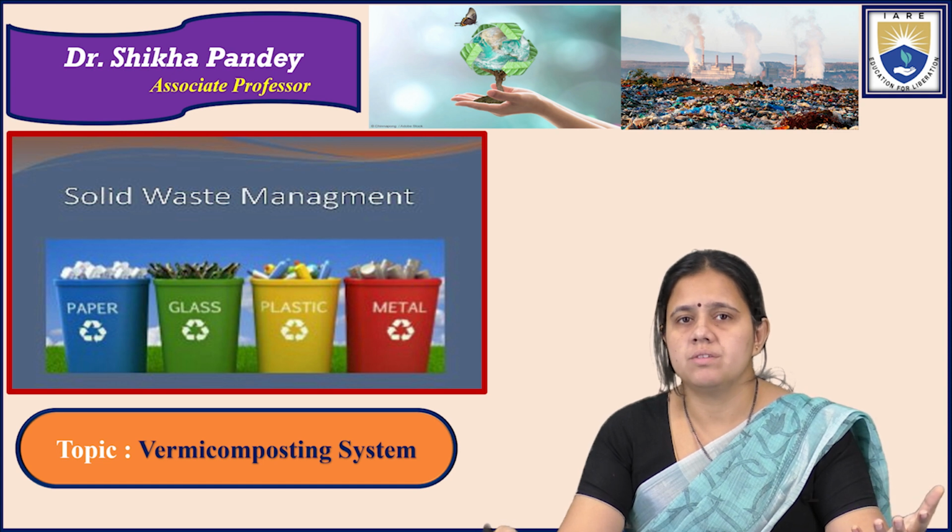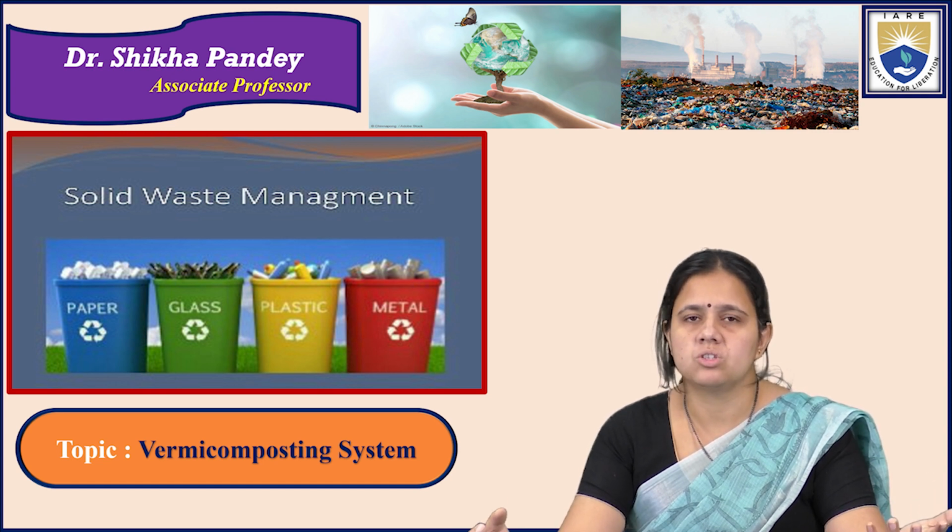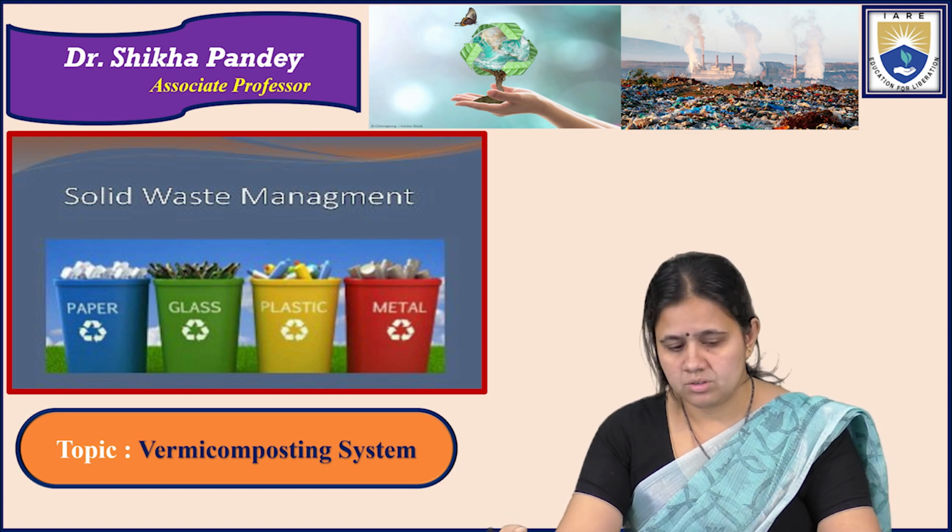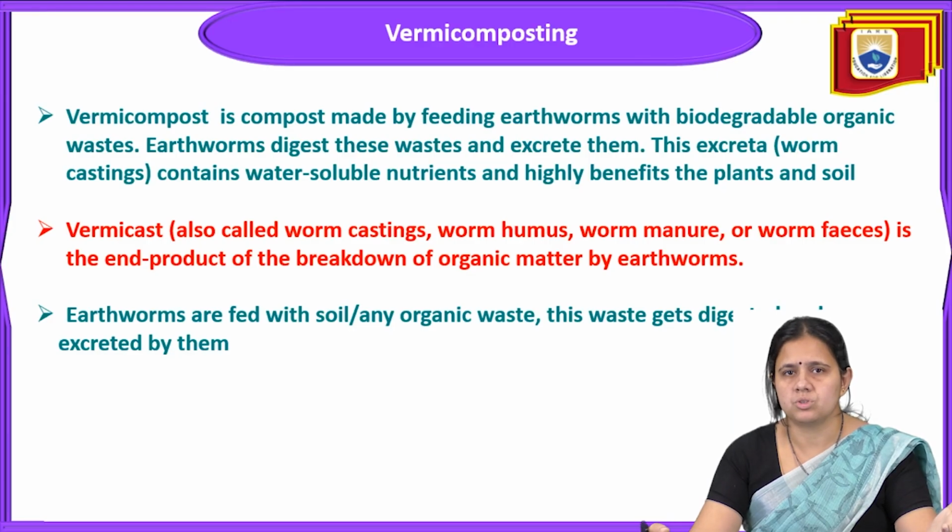It involves the use of earthworms to degrade the solid waste or the organic matter present in the solid waste. So vermicompost is a compost that is made by feeding earthworms with biodegradable organic wastes. In that waste, we feed some earthworms, and those earthworms degrade the organic matter present in the waste, digest it and excrete it.